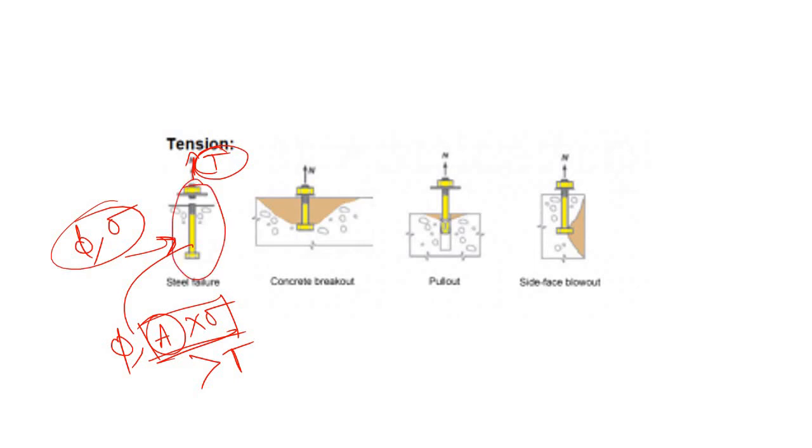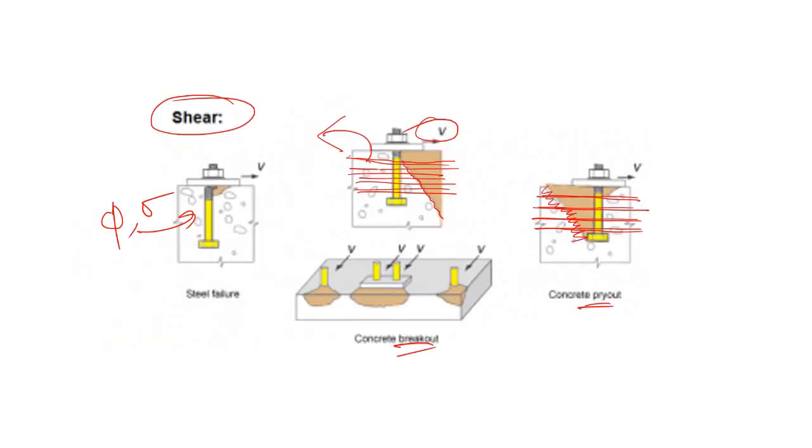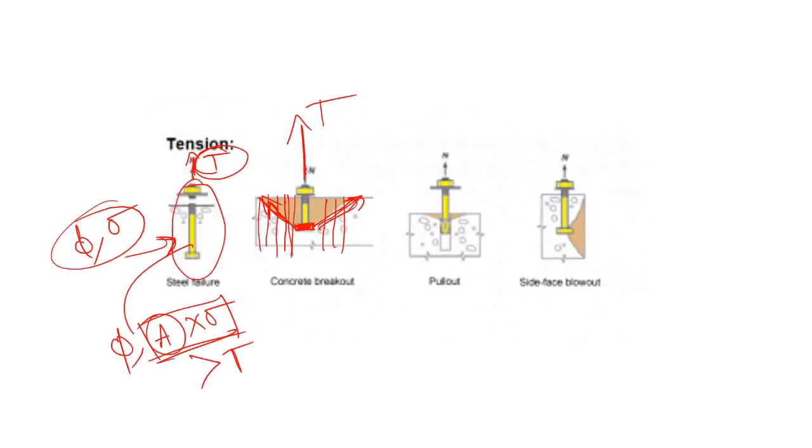Now what can happen if you have sufficient strength to carry the tensile force? Then it will transfer this tension to the concrete like this, because the bottom has some anchorage by using some washer or bolt. So now this whole concrete zone is trying to go away due to this tensile force. To resist this crack again, you have to provide some reinforcement like this. Initially, due to shear, we provided the horizontal reinforcement. Now due to this tension we are providing the vertical reinforcement.